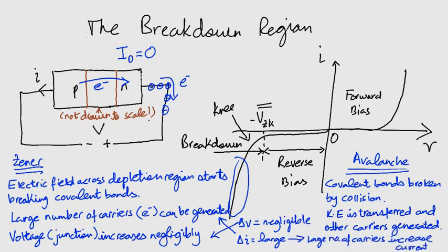So what is the limit to which we can increase the reverse voltage? The process does not destroy the device as long as the maximum specified power dissipation is not exceeded. This is the safe limit which determines the maximum allowable reverse current. We will study Zener diodes and their application in future lessons in this module.